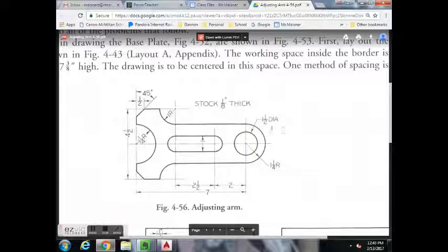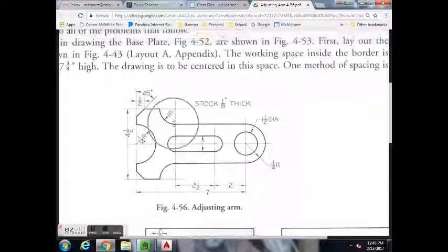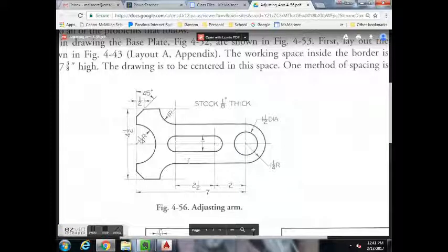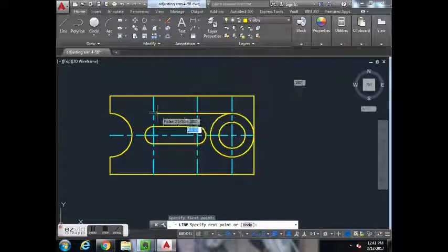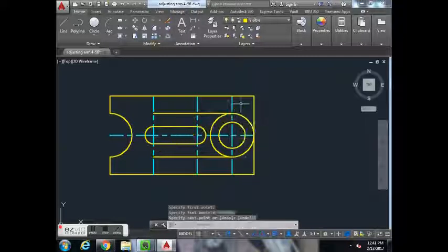So the next step would be to create these lines coming down to here. So we have a line from this top of this circle over to here, and then this half circle, which we'll get later. So let's put these lines in. So we'll go to the line button, top quadrant, draw a line to this intersection, hit escape, line to this intersection, hit escape.